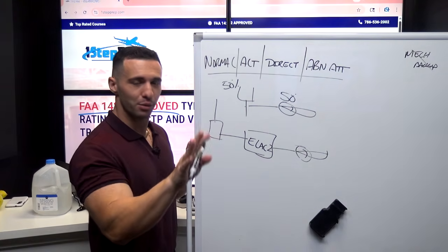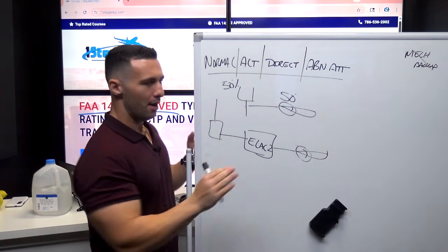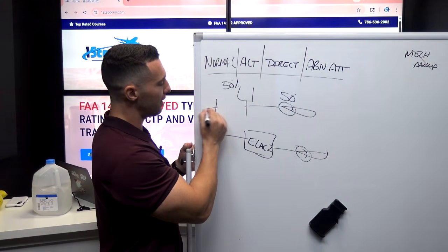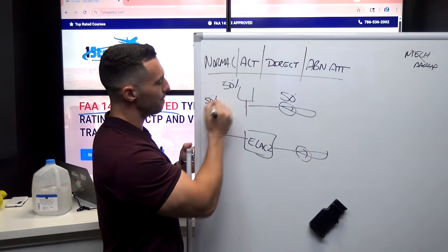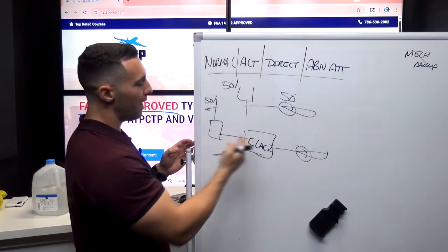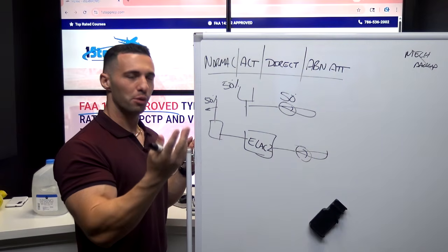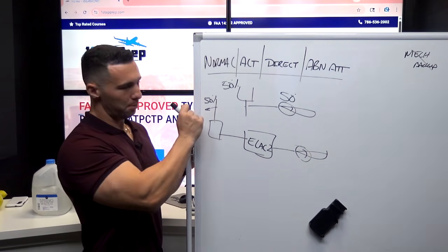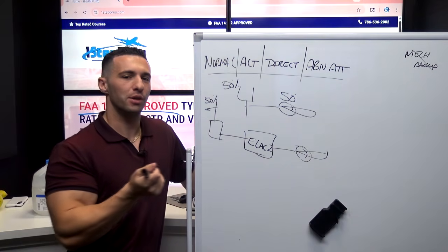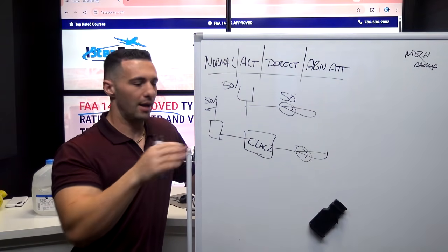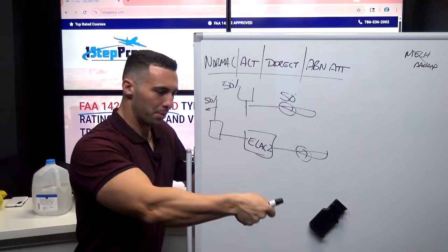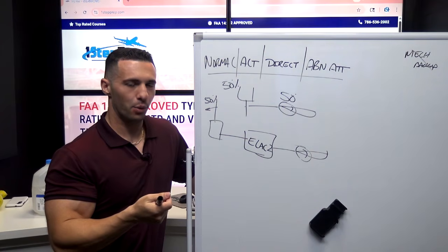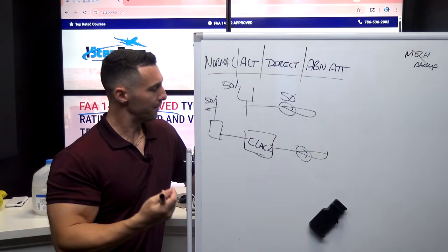And effectively what I want to share with you here now is just to bring some clarity to this, is that my elevator is going to move proportionate to the command of the ELAC, which is not necessarily proportionate to the command of the side stick by means of displacement. Simply put, here's what that means, very simply put. If I take the side stick and I deflect it aft, say 50%, the ELAC takes that input and it interprets it as a positive G change request.